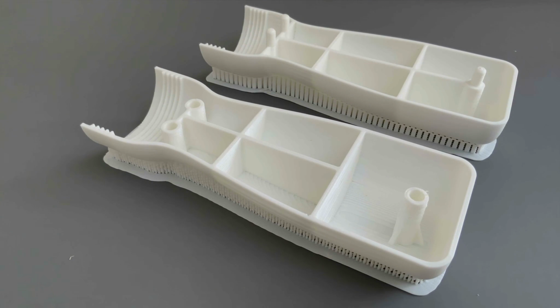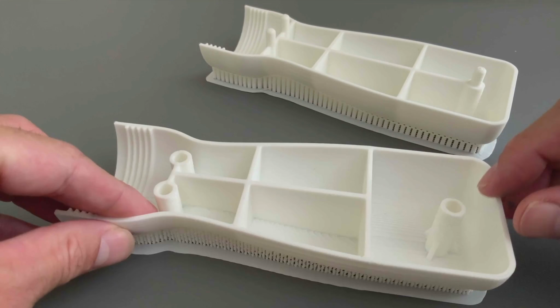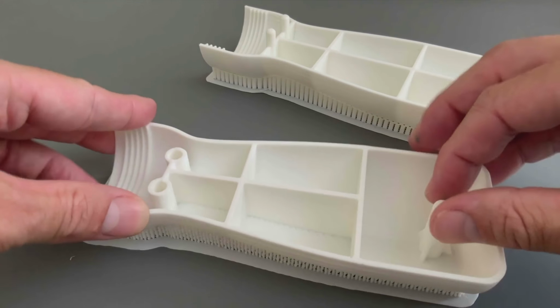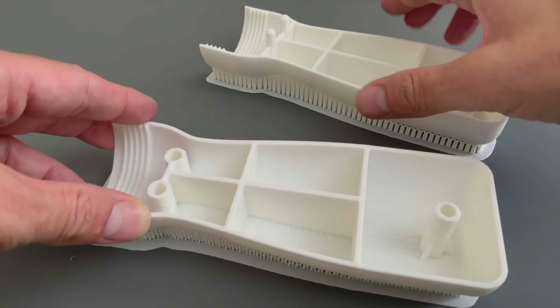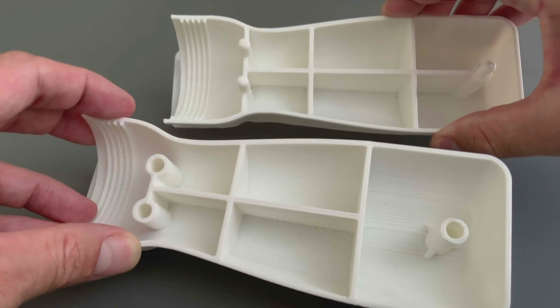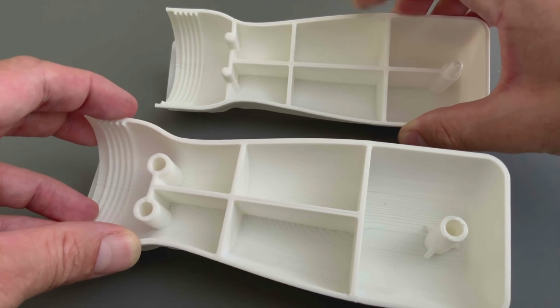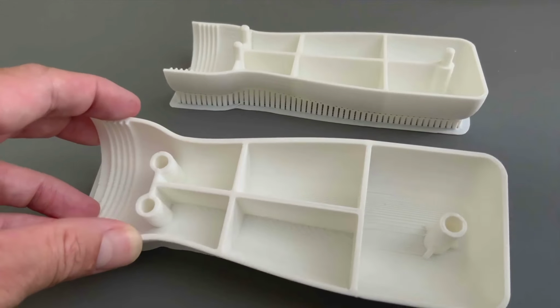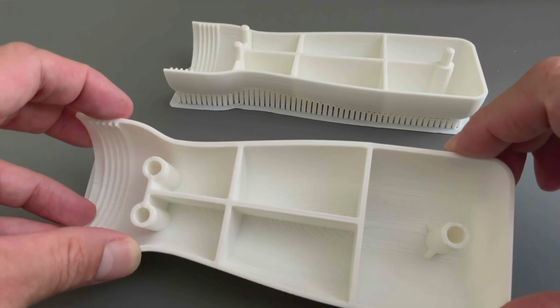In terms of stability, 3D prints with fused deposit modeling are layered, which means you can see all the layers. When we have a small object, if I press really hard, I can break this off. So to stiffen up bigger objects or to add stability to small extrusions, we can add a web or add ribs. And I will show how we do this.